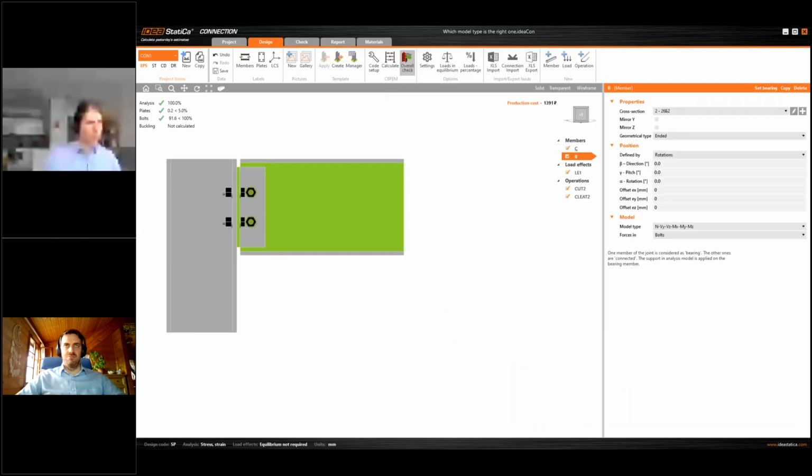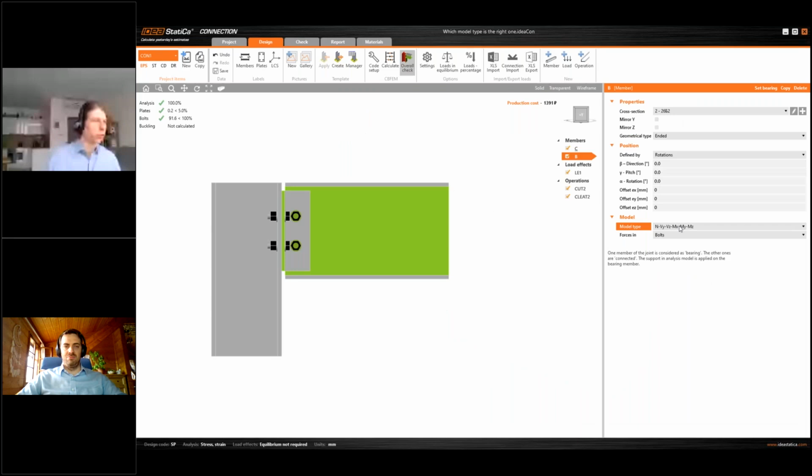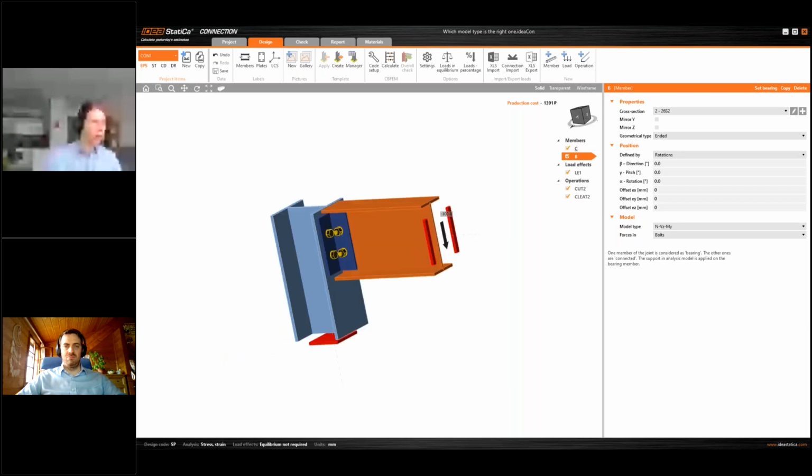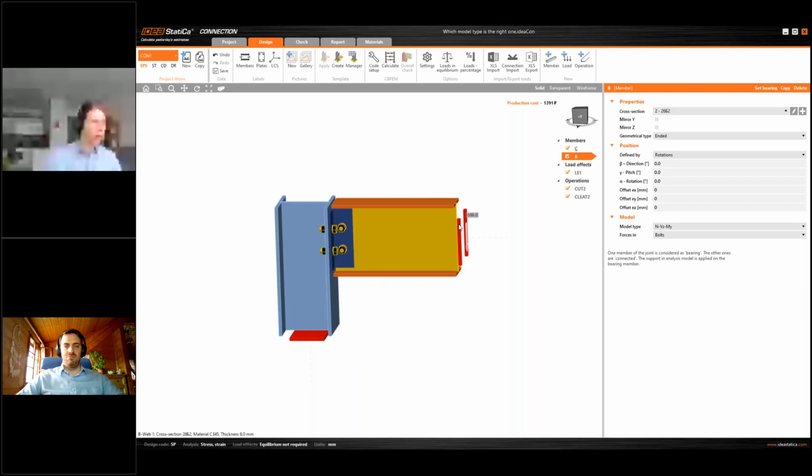So the general one is recommended to use for any kind of connections. These side restrictions mean the beam closely at the location close to the connection I'm analyzing here is somehow supported in this way. There are, for example, side beams holding this beam in position and taking the loads and stresses in this direction. Same in here. This is now supported by some column in this place.